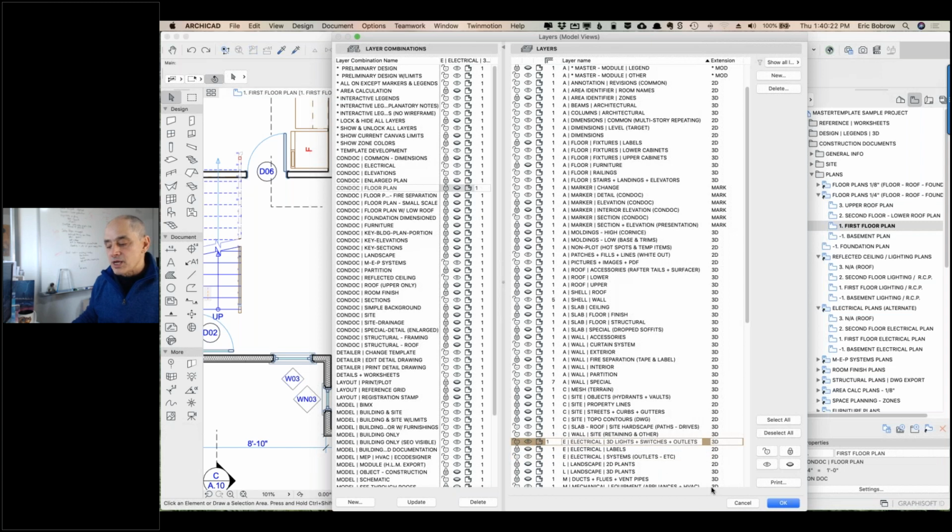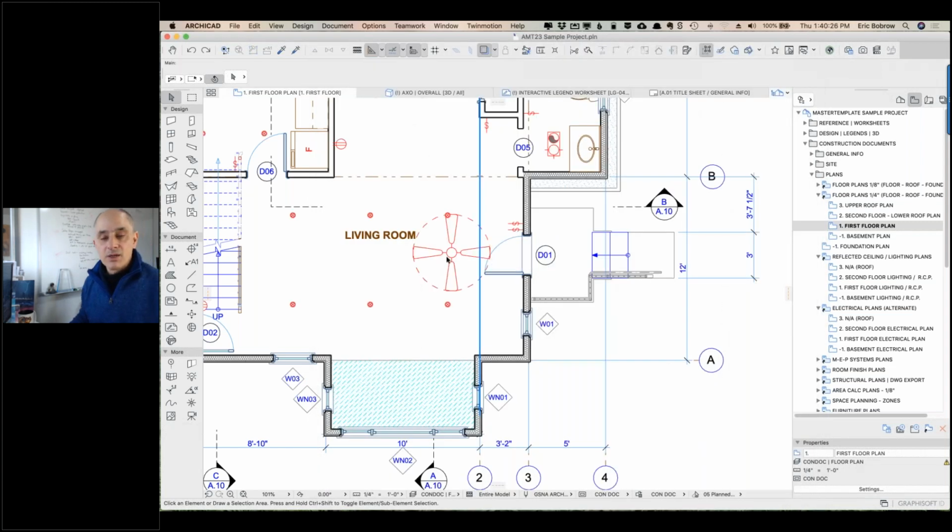So they'll just manually change that and say okay, which means that you will start to see these elements, but then you go off and do something else and you come back and these elements are no longer visible, and these newer users tend to go, I don't know, I drew something, but I can't find it. I don't know what layer I put it on. So in general, what you want to do is pay attention to the layers.